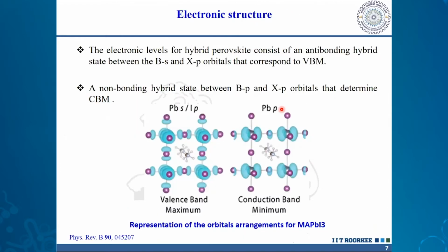So now we are interested to see this material, which shows a very peculiar type of electronic properties. This material is an ambipolar charge transport material, where the electron and hole transport happens inside the same material. And the binding energy of these electrons and holes is much less than in organic materials. So with a very limited amount of energy, this material can at room temperature dissociate into free charge carriers and contribute to the current.